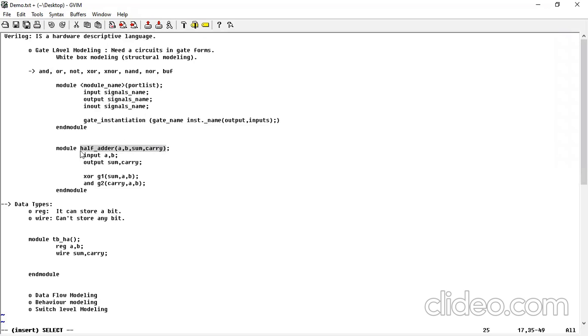Okay. So here you have instantiated XOR gate, AND gate. These are predefined gates, right? But half adder is user defined. We have defined it already. So module names should be the same to call this. So what is our module name? Half underscore adder. Okay. Again, instantiate name. You can keep anything in instantiate name. So we have kept here half adder, HA.